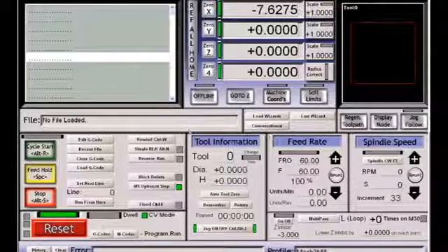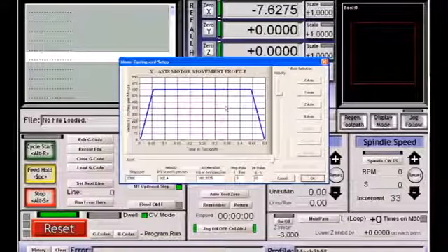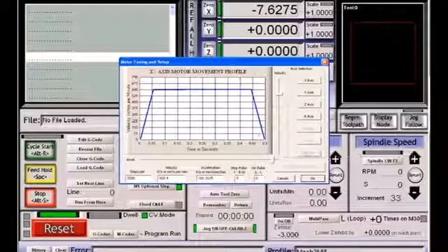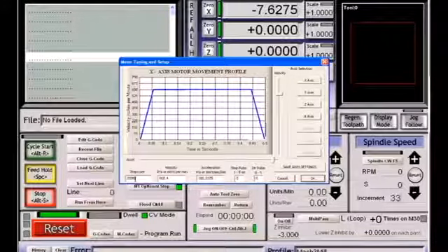So now we have set up our motors and we want to move down. The next step that you need to do to get basic movement is motor tuning. So we'll go to the motor tuning stage. The first thing that's important is how many steps per unit it takes to move your table. As I said earlier, we set ourselves up for this machine in millimeters, so the steps per here refers to millimeters. Steps per millimeter, I have mine set to 2,000. If you don't know your steps per millimeter, we can calculate it out pretty easily, but use 2,000 as a